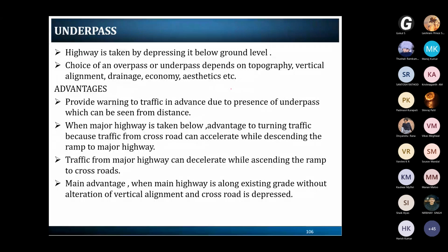And when it comes to the underpass, the road will be below level. So this is based on the conditions, what we want to provide accordingly. You choose the overpass or the underpass based on different kinds of testing, and even the soil test plays a major role. So accordingly we are providing. The presence of the underpass can be seen from a distance, and proper warning to the traffic is given well in advance.